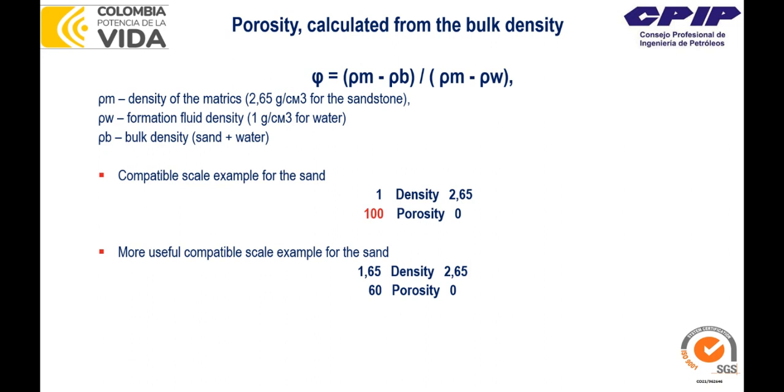The slide illustrates the relationship between density and porosity, as explained in the following paragraphs. The equation you see here assumes the fluid is water. We select a sandstone or limestone matrix and the bulk density from the zone of interest. For example, if 2.65 and 1.65 grams per cubic centimeter are converted to density-derived porosity for a sandstone formation, the values would be zero porosity for 2.65 grams per cubic centimeter and 0.6, or 60 porosity units, for the density value of 1.65.